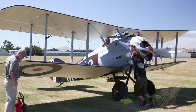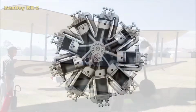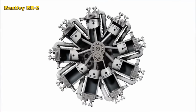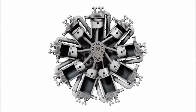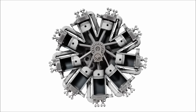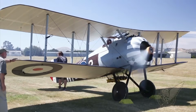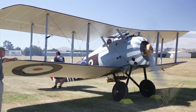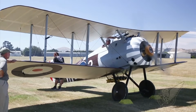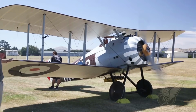The last rotary designs could be found in aviation in the early 1920s, and the British 9-cylinder Bentley BR2, developed at the end of World War I, is considered the most powerful engine of this configuration. And in fact, the BR2's performance figures were at the limit. It was impossible to further increase displacement, rotating mass, power, or speed. The 25-liter Bentley BR2 produced about 230 horsepower and weighed 220 kilograms.